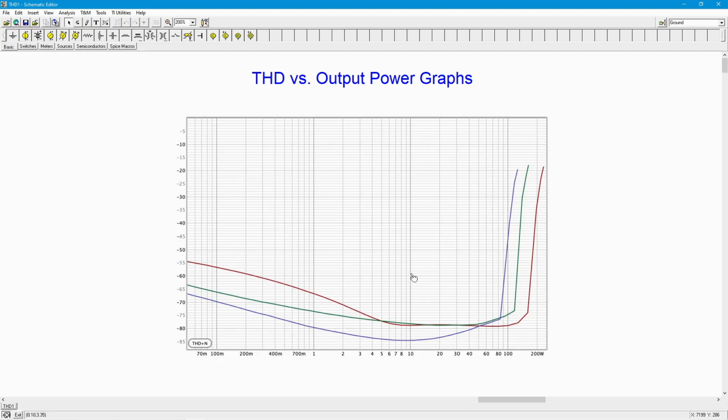Now, if you had headphones, you can swamp out that background noise. So you might make an argument that with very high quality headphones, you might need something a little bit less than that, a lower number. But it's not going to be a huge value, because don't forget, headphones and certainly loudspeakers at low frequencies create a considerable amount of THD themselves. That's really the weak link in your playback system, not the amplifier.